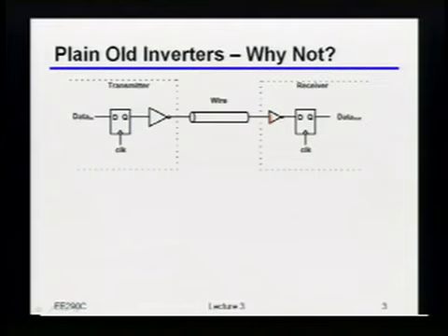Let's throw that out to you guys. What's wrong with building a link this way? What are some of the issues you can think of? And I mean specifically, it's actually not just the circuits. Okay, well, you said it's single-ended. Now, we're going to talk some more about that. That in and of itself is actually not a bad thing. Single-ended means that in theory I only have one wire instead of two, so I could even argue that there's an advantage. But what are the problems with it being single-ended? Just the noise immunity.